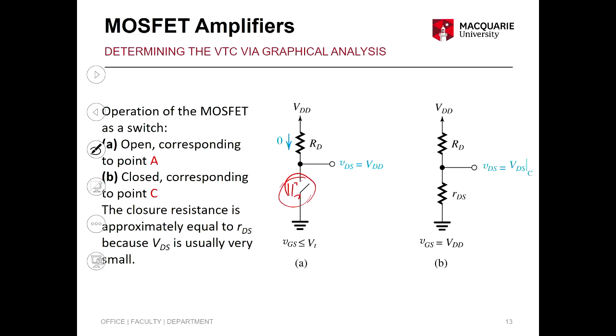The benefit of the transistor is that we know it's a 4-terminal device. We actually ground the bulk, which is the B terminal. Then we have one terminal controlling the other two major signal terminals. When you control the VGS, you can configure it so that if VGS is lower than VTH, then it's an open circuit.